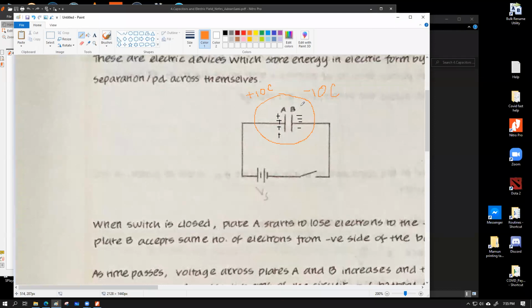So if that's the case, then let's say you make a statement that a capacitor is currently holding Q coulomb charge, or the charge stored in a capacitor is Q. In many cases, we're going to come across this very usual statement. It's not wrong. If we say that a capacitor has a charge of Q coulomb, or Q millicoulomb, microcoulomb, whatever, that essentially means the magnitude of charge in one of those plates, not on both the plates. Combined on both the plates, the total charge will always be 0.